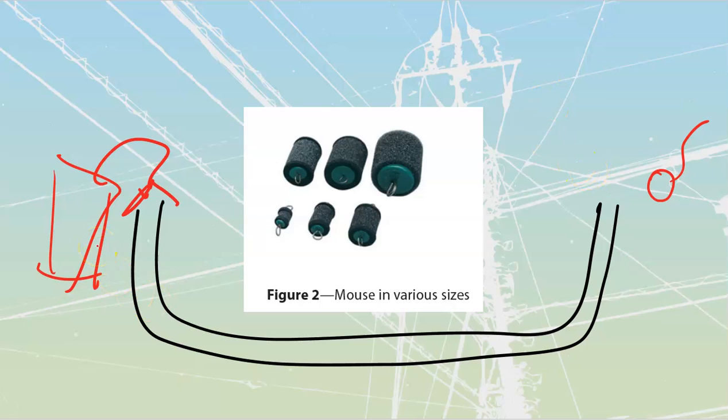Always start first by cleaning the conduit out. First thing you should do if you're going to vacuum, all these shop vacs have the option to blow as well. Do not uncap a set of conduits and then pull it through your vacuum, because your vacuum has this thing called the AC series motor that has brushes. If this conduit was glued together and capped, all of those fumes are still inside of it. There are numerous people out there that have experienced vacuum cleaners going boom, which is the sound of a small explosion inside of them, because they're pulling in all of this fuel-air ratio that's inside of here into there, running it over top of the brushes, and you get a big pile of flame that comes out of the outside of your vacuum cleaner. Not healthy for you, for the vacuum cleaner, for anybody.